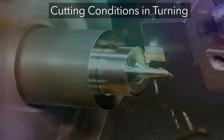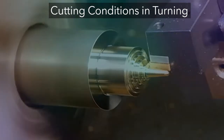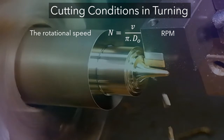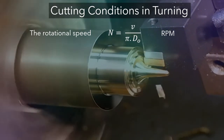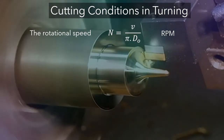The rotational speed in turning is related to the desired cutting speed at the surface of the cylindrical workpiece and is given by the equation. N is the rotational speed, V is the cutting speed, and D0 is the original diameter of the work part.